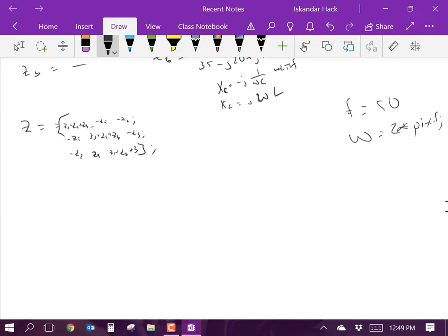And then you can say ZX is equal to 30 plus j omega 10e negative 6, for example, or negative 3, where that's a 10 millihenry inductor, for example. Well, we'll go through that. I don't want to go through this right now, but you could do that.